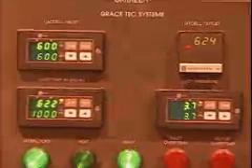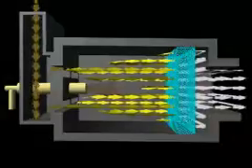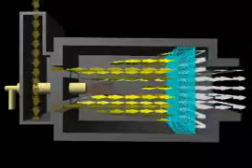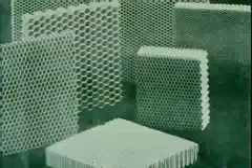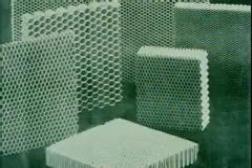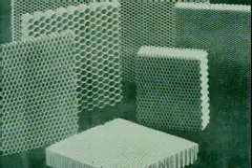Catalytic oxidizers are used for contaminated gas streams that have an organic vapor concentration that is less than 25% of the lower explosive limit. Concentrations greater than this cause high temperatures that can damage the catalyst material. A catalyst is a substance that accelerates a chemical reaction without undergoing a change itself. The typical catalysts used in incineration are noble metal oxides of platinum, palladium, or rhodium that are deposited as a thin layer on a high surface area support material. Base metal oxides such as vanadium pentaoxide, titanium dioxide, or manganese dioxide may also be used.